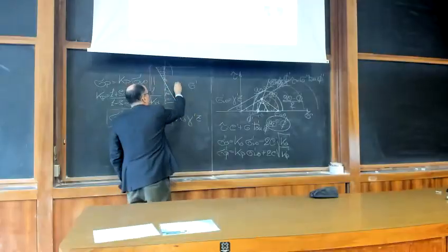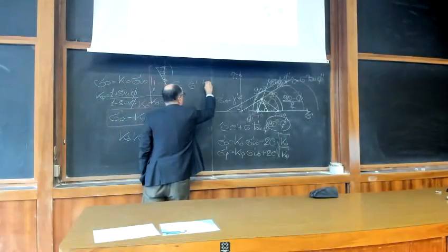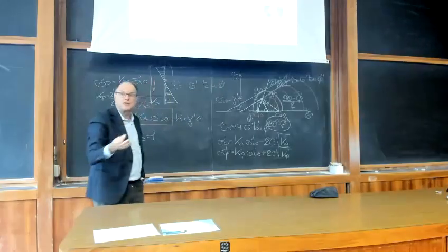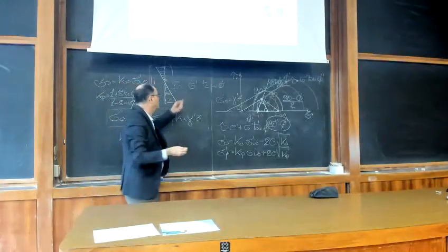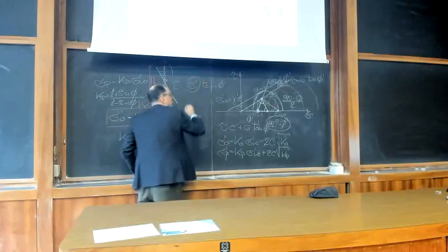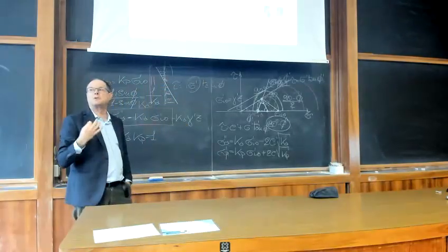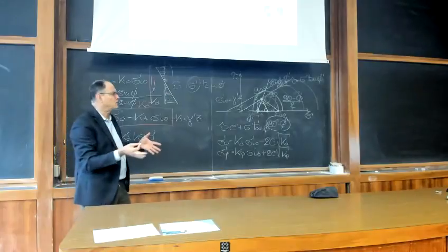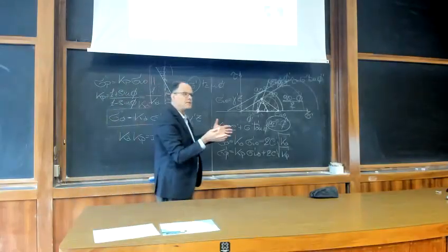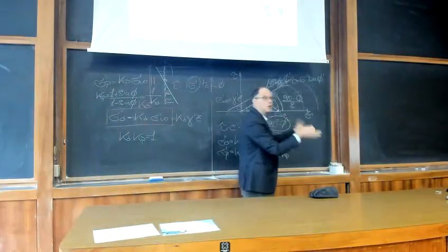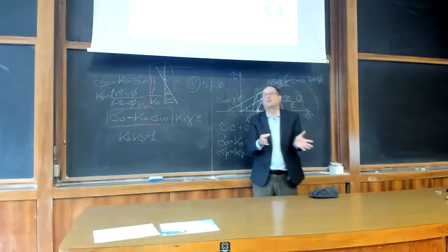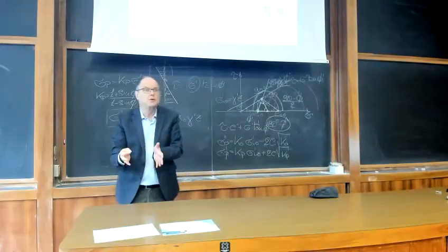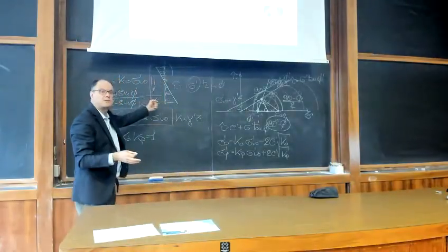We have seen, for example, the strength depends on the Mohr-Coulomb criterion. The stiffness of the soil depends on the effective stresses. All the soil properties depend on soil stresses. So once you want to run a physical experiment, like loading a foundation, you need to replicate in the laboratory, at a small scale, the same stress field.